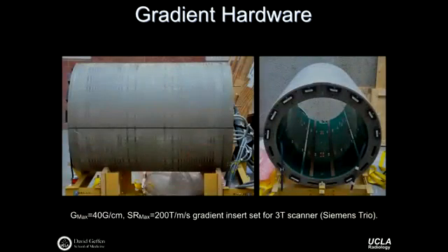When these gradient coils come out of the scanner, this is the one that was removed after one of our upgrades, you can more easily see a Z gradient coil. And so here you can see the coil windings. This is all embedded in epoxy fiberglass resin. You can see the coil windings. And they don't have exactly a simple solenoidal shape, meaning a uniform current density, but they're wound in such a way to produce the fields with high linearity in the region of interest. So you get just some different views of the gradient coil once it's actually been pulled out of the scanner.